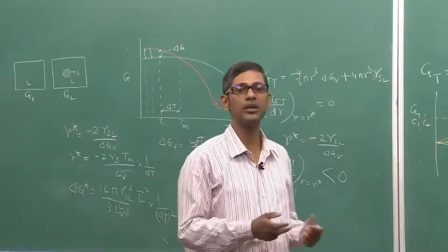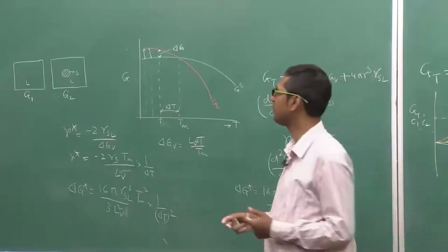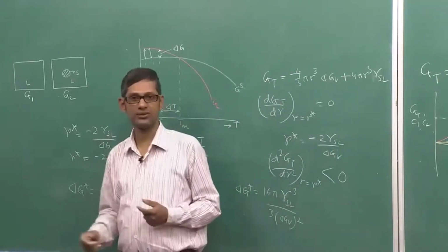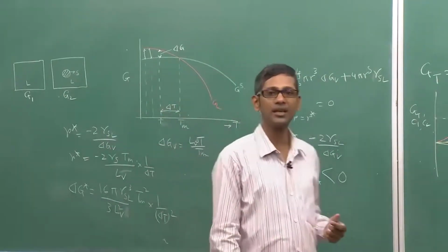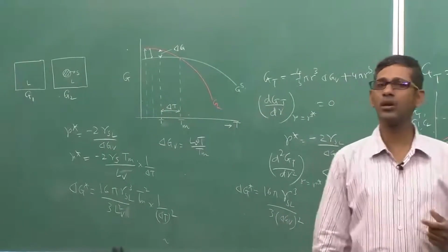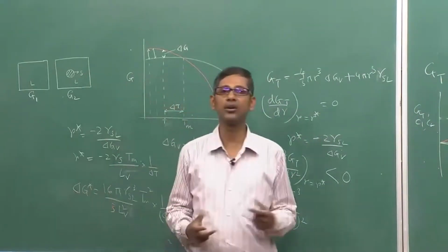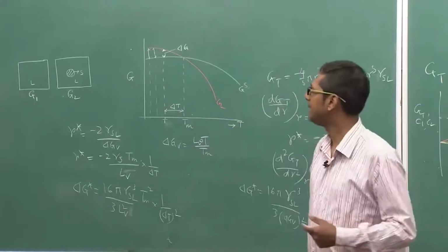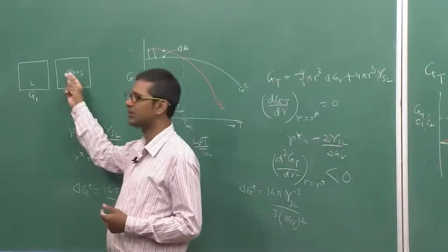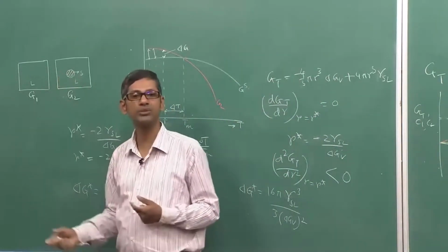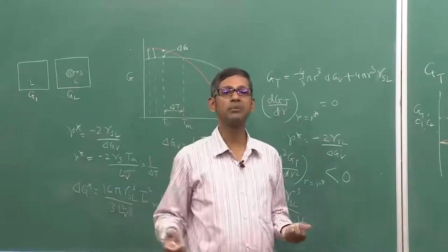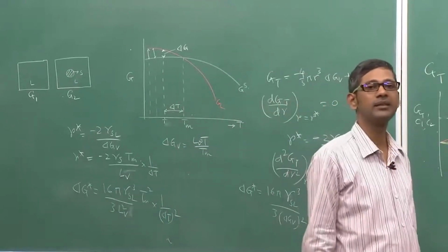The densities of solid and liquid are not the same. Because of that, there is a volume change, and this volume change in a liquid to solid transformation will not affect anything in the liquid, because liquid cannot take up any shear. Therefore, even if there is a strain or stress applied because of this volume change, this can be easily accommodated in the liquid. Okay. That is very simple.